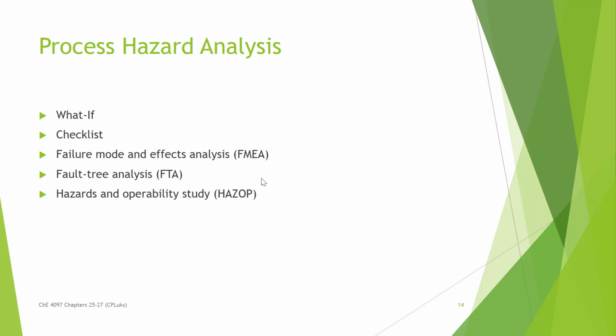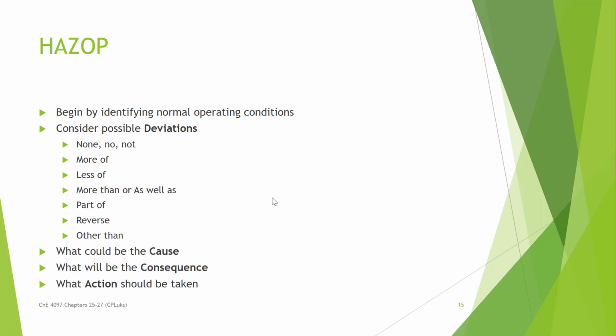But you can do failure mode and effects analysis, a fault tree analysis, a hazards and operability study, a hazards analysis, a HAZAN, lots of different things there. Most of you have been choosing the HAZOP. To do a really full HAZOP would probably take a dedicated week, and knowing more about the details of our system than we know right now.